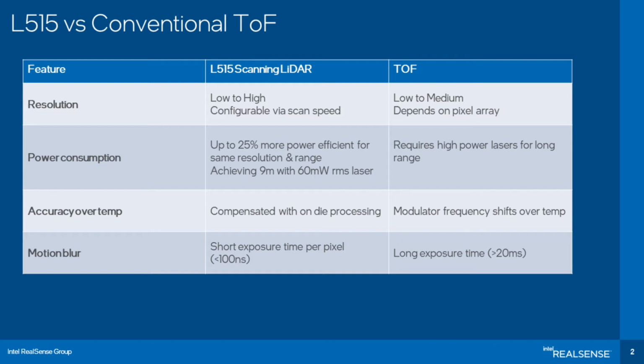A modulated laser signal collected with a single APD per pixel is more power efficient compared to flash-based solutions. The L500 technology supports field of view changes by repositioning the MEMS mirror. And finally, very short exposure times made possible with LiDAR virtually eliminate motion blur.